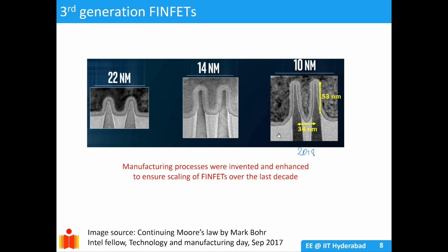So this is new technology. New manufacturing processes were invented and enhanced to ensure scaling of FinFET over the last decade. You can see going from 22 nanometer to 10 nanometer how FinFETs have scaled, with the distance between FinFETs reduced, and the height of the fin increased.